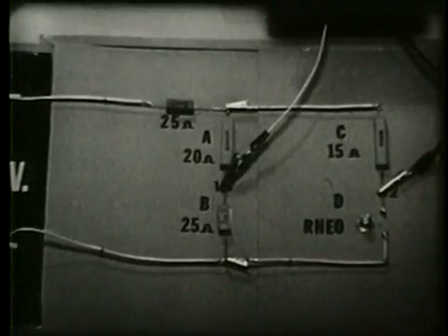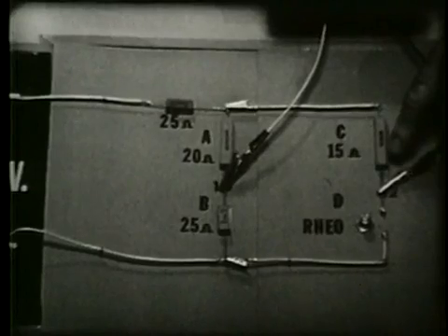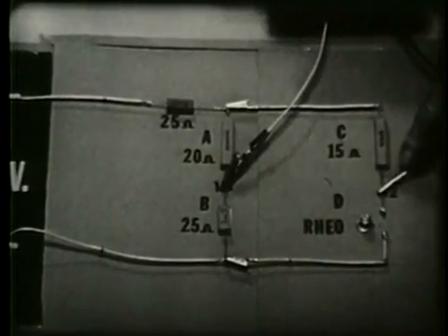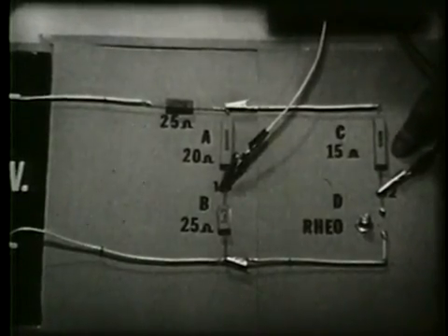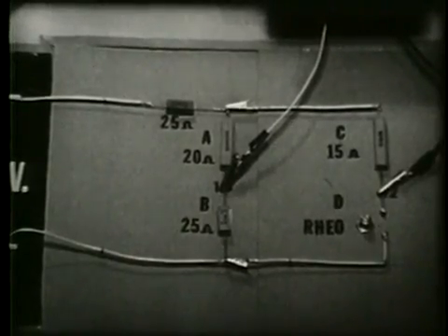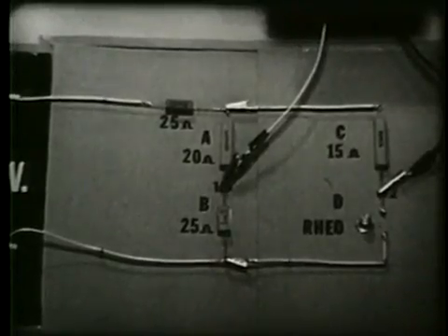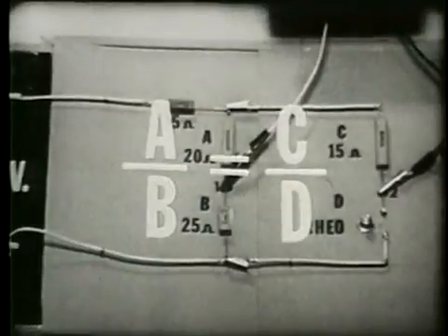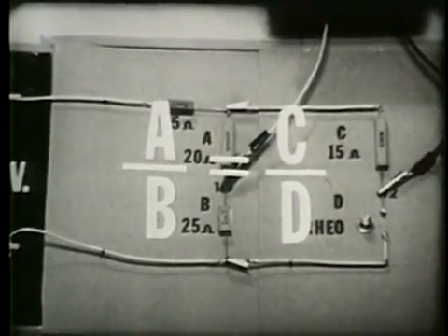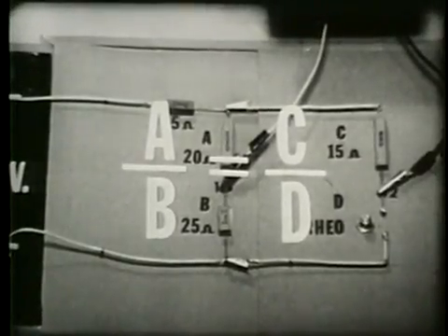What does this have to do with resistance? We have a direct relationship between the resistance and the voltage. The voltage which appears across a resistor is directly proportional to the resistance. This means that in a balanced bridge, we have exactly the same ratio for the resistance as we have for the voltage. With this ratio, when we know the value of any 3 resistors, it is a simple matter to calculate the value of the 4th resistor.